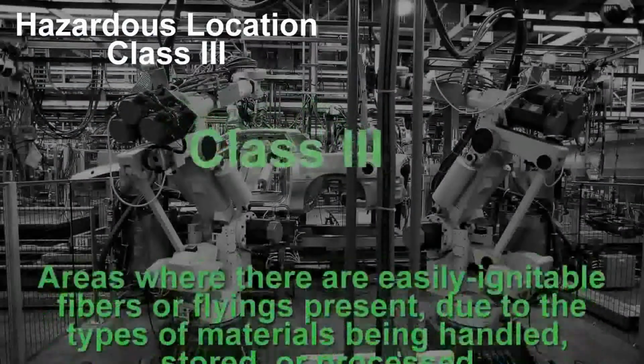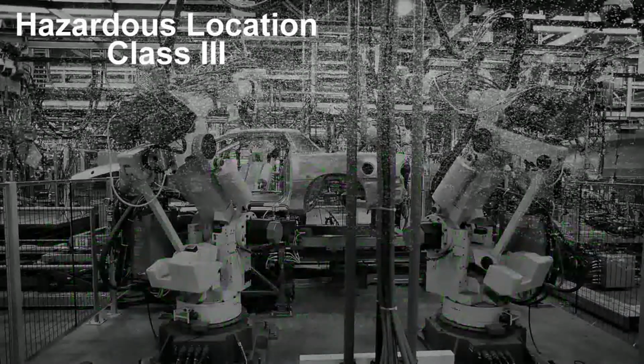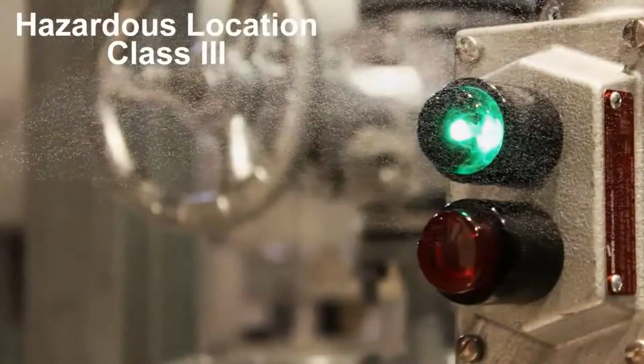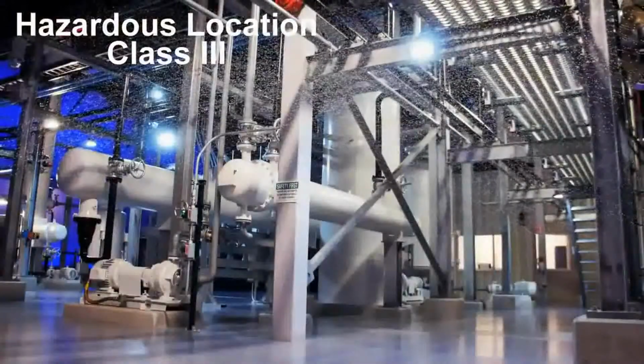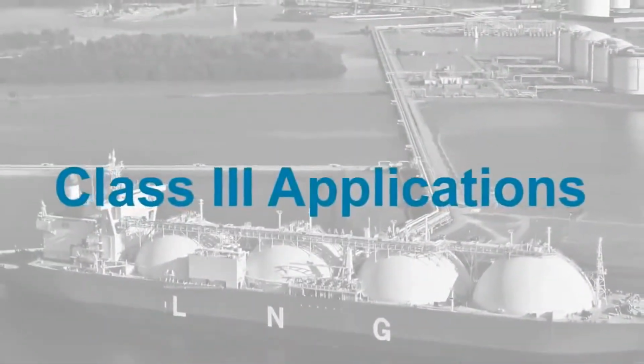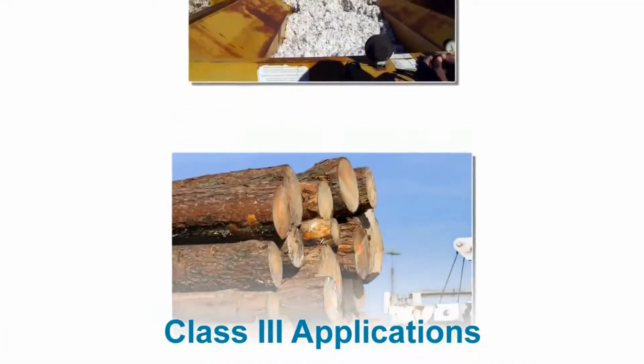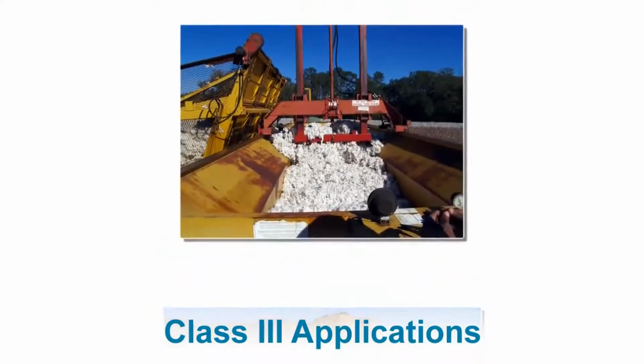Class 3 hazardous locations, according to the NEC, are areas where there are easily ignitable fibers or flyings present due to the types of materials being handled, stored, or processed. The fibers and flyings are not likely to be suspended in the air, but can collect on machinery or lighting fixtures where heat, a spark, or hot metal can ignite them. Some typical Class 3 locations are cottonseed mills and facilities that shape, pulverize, or cut wood and create sawdust or flyings.